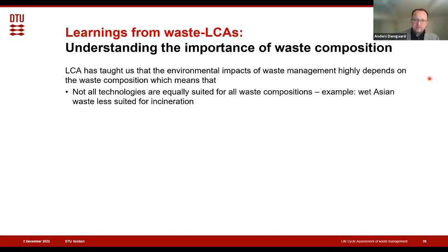This is because in a context like Denmark, residual waste has an energy content of 10 to 12 megajoules per kilo of wet weight, where in Asia, that would probably be somewhere around 3 to 4 megajoules per kilogram of wet weight. And that can actually mean you might not be able to burn it without adding other types of waste that can increase that energy content.